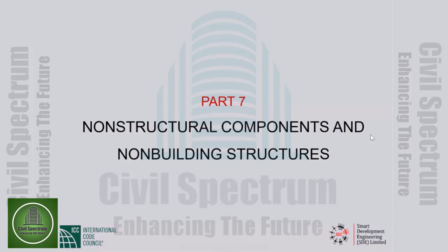There are diaphragms that are prescriptively flexible without having to do deflection calculation, and there are diaphragms that are prescriptively rigid without having to do deflection calculation. If your diaphragm is neither prescriptively flexible or prescriptively rigid, then you have to base your definition on calculated diaphragm deflection. And that's where I think your SDI document comes in. It will tell you how to calculate diaphragm deflection. But the definition is in section 12.3 of ASCE 7-05, and that's where you need to look.